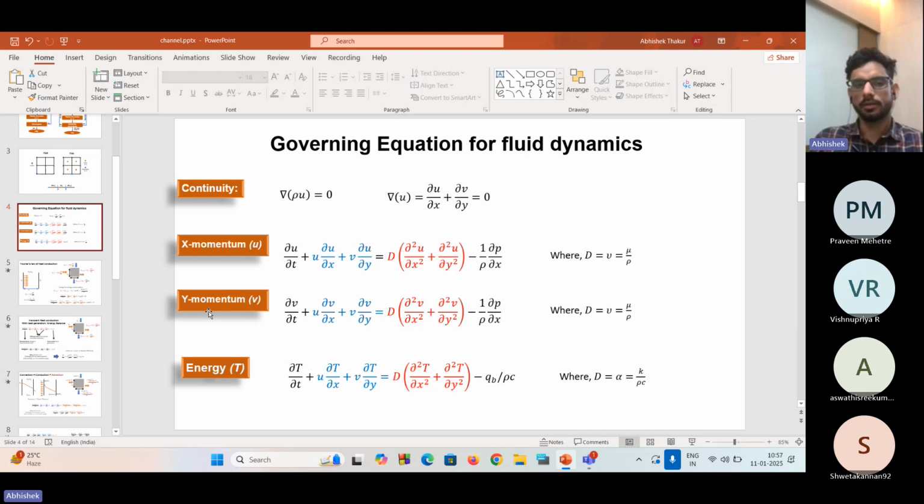If you use Reynolds averaged Navier-Stokes equations for turbulence, some models have one extra equation, two extra equations, and some models have six extra equations. So it is computationally very expensive. It is always better to avoid turbulence models wherever possible.